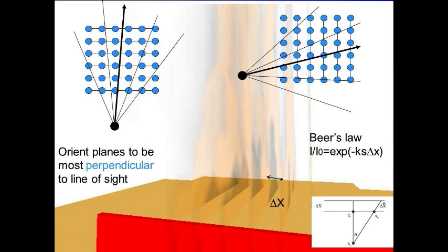When you're looking at it in Smokeview, I'm always drawing it so that you're looking at it full face on. So I want to orient the planes so that they're as perpendicular to you as I can make it. For the purposes of this illustration, I turn that off so that you can see them from the side.